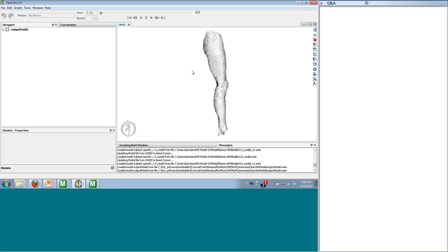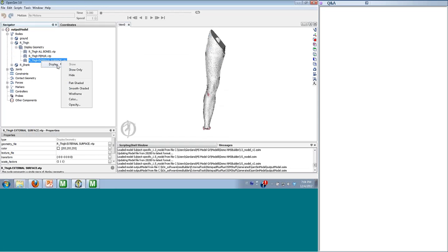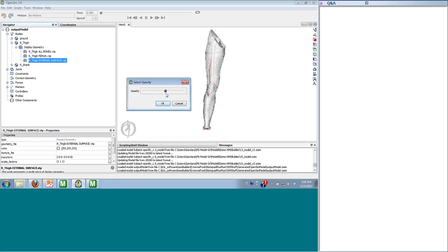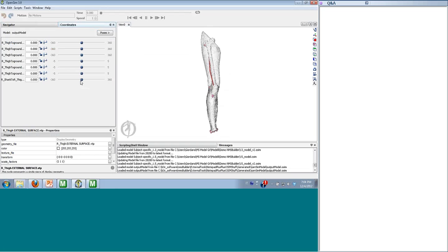And here it is. This is exactly the model subpart that I just created. So here, if I go and navigate all the elements, you see all the different bodies. So for example, under right eye, I can display geometries. I'm going to decrease a little bit the opacity to let you see. So the other tissue and the muscle actuators that I've defined. You can move the body, so see the generalized coordinates and see that I have properly defined the knee joint.